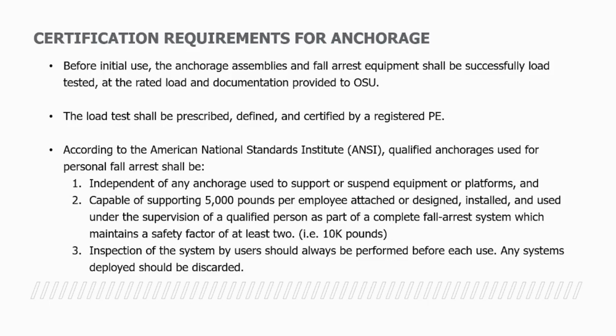It shall also be capable of supporting 5,000 pounds per employee attached, or designed, installed, and used under the supervision of a qualified person as part of a complete fall arrest system, which means a safety factor of at least 2. Okay, if you have 5,000 pounds per employee, that's going to be a safety factor of what? 10,000 pounds.